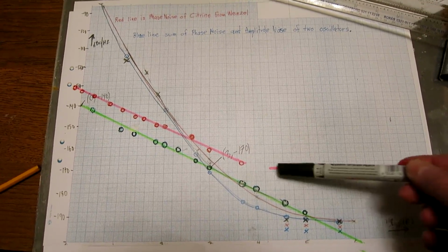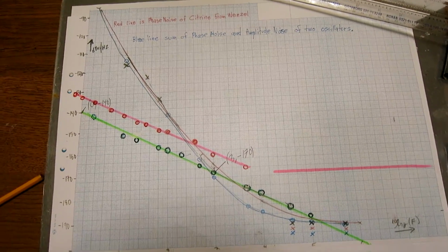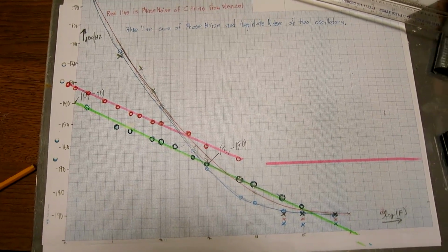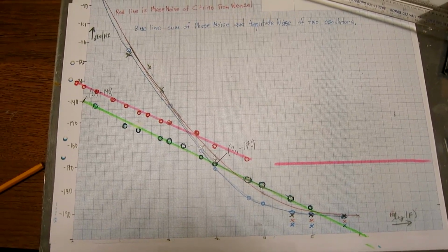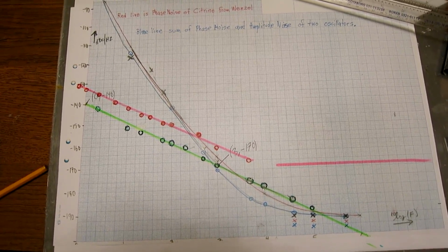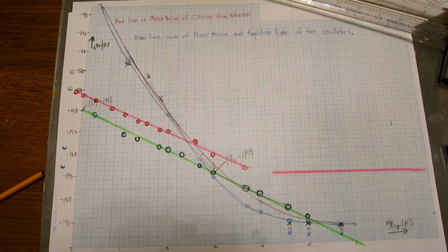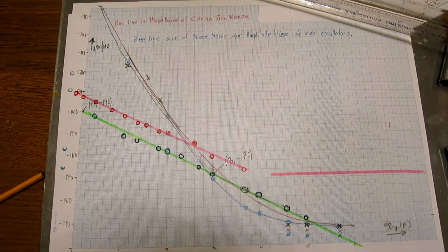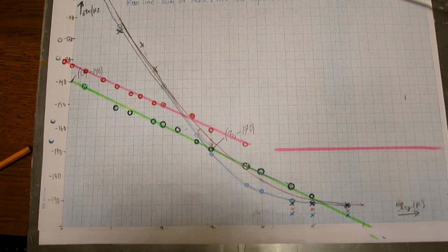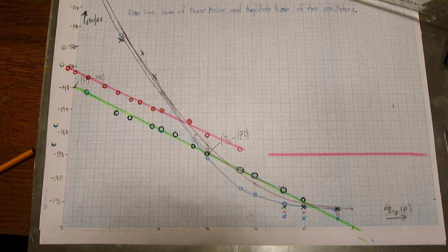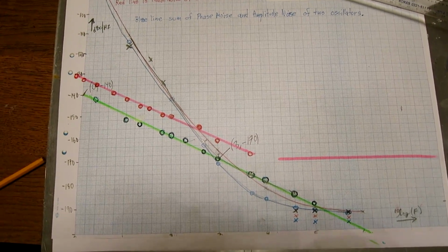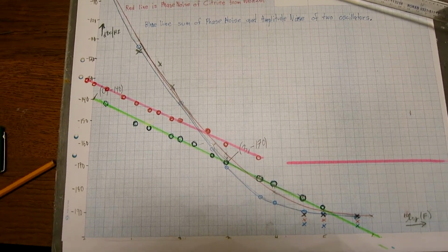But this thing here, if we reduce the carrier level, that will degrade significantly, even though the noise figure might be a little bit better, because there is some loss of noise figure when the unit goes into compression. But I think this is about the optimum one can get from this amplifier.